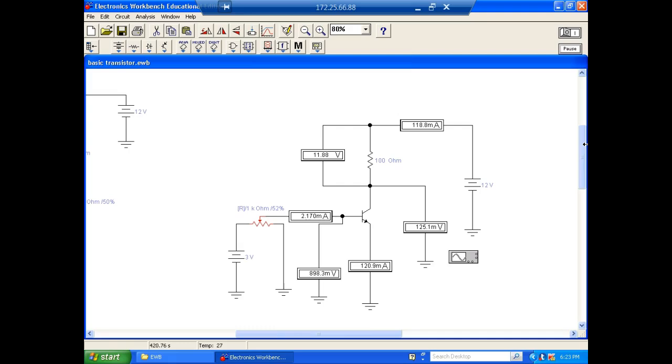So my amplifier is operated in the active region, where I'm using my input signal to control the base current, and I get a lot more collector current than base current, which is pretty neat. To operate it as an amplifier, like a stereo amplifier, those types of amplifiers, we operate these things in the active region. Oops, sorry, guys. Let's go back down. So now we're saturated.